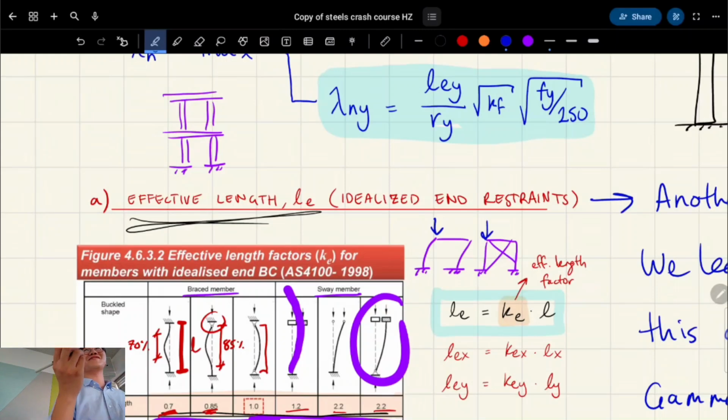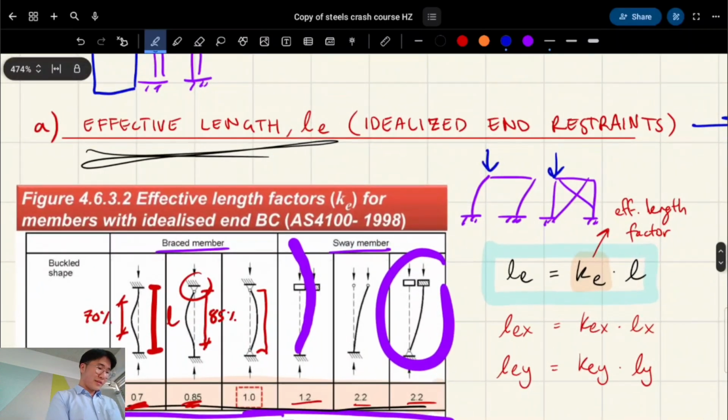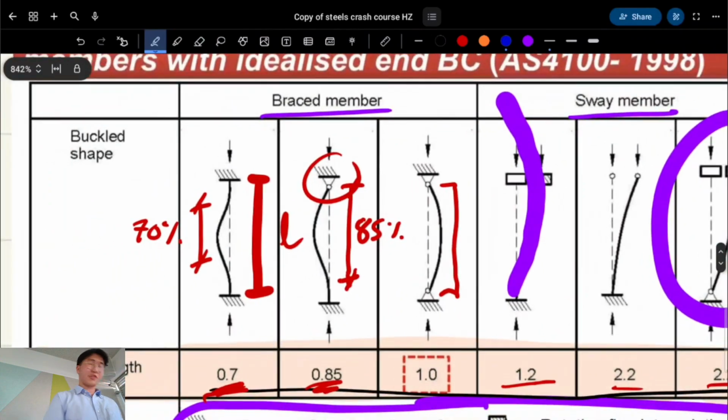You don't want to be in a building that sways around, right? So what they do is they put a concrete core in. That's usually like an elevator shaft with really thick concrete walls, and so it doesn't shake around. That's their way of essentially making it braced, right? Okay, so say it's braced, based on the end conditions, right? Like the end restraints. What do you think that building's K factor might be in the ballpark of?